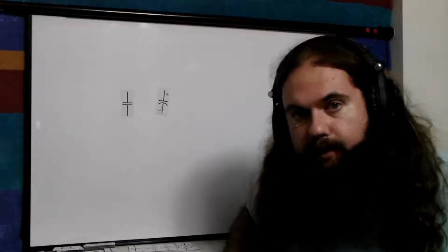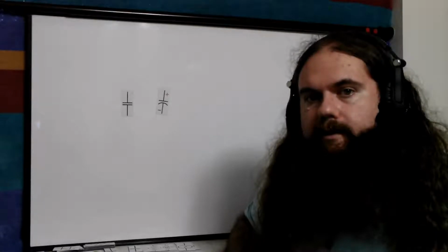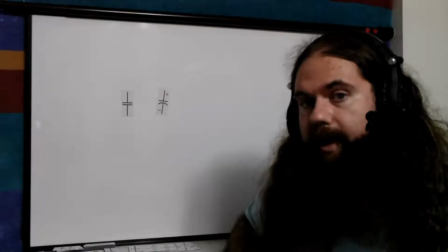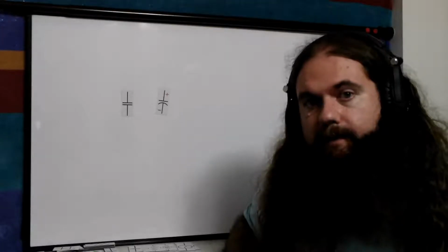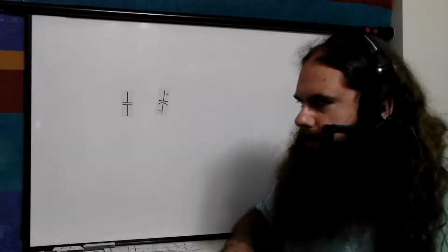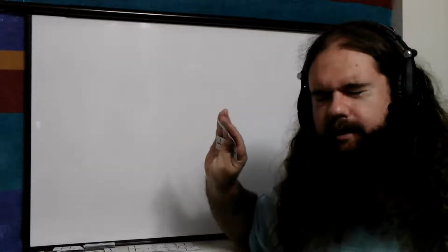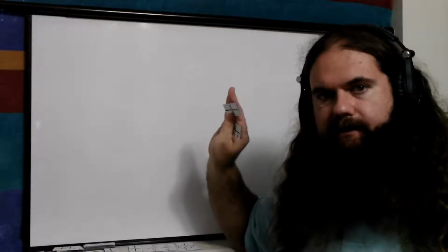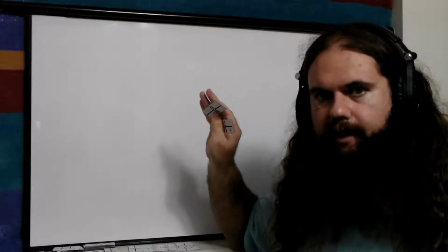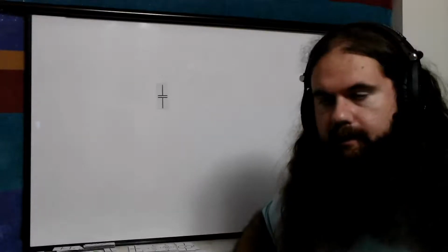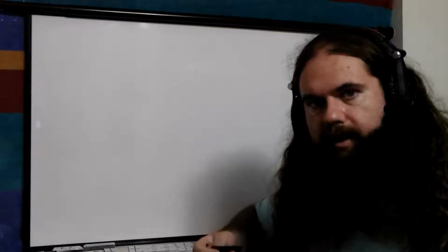And it's a very common point of failure for old computers, such as one particular example I know of is some of the old all-in-one Macintoshes back in the good old days. You know, the beige toasters. It was quite common in them to have to replace capacitors to get them working again. So whenever you see polar and nonpolar in a circuit, generally the reason is for cost. And the reason for specifying it's a polar is just to make sure you don't hook it up the wrong way. There is no situation whatsoever that you couldn't take a polar and replace it with a nonpolar. It'll just cost more. And depending on how you make the nonpolar one, it might be a different size.